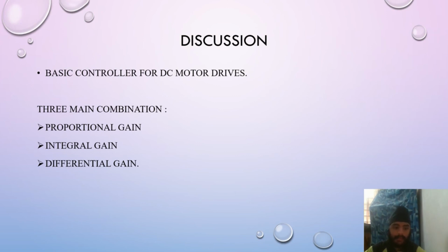The current is set to be proportional to the error. If the proportional gain is very high, the system could become unstable. But if the proportional value is very low, there will be a large input error and the system will be less responsive. Meanwhile, integral gain improves the performance at lower frequency, and differential gain, on the other hand, gives incremental improvement at a much higher frequency for the system.